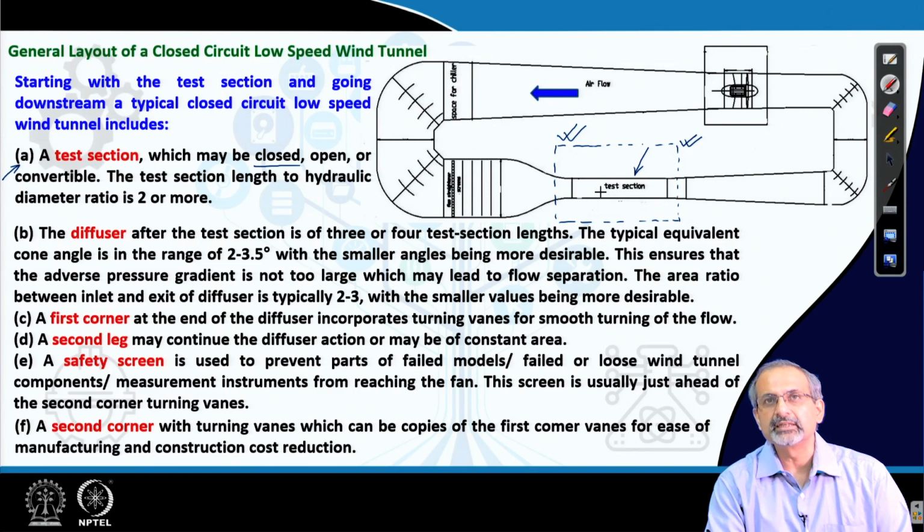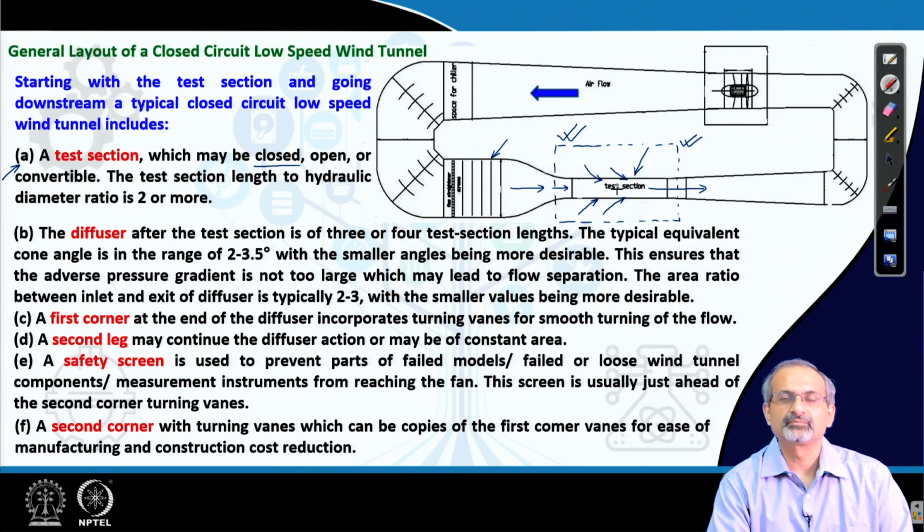Additionally, in open jet facilities, if you do not have an enclosure around the test section, there is often a problem that instead of the air coming in from the settling chamber and the contraction section, a large part of the air gets dragged from the ambient into the jet and then continues into the diffuser. Therefore, the jet gets extremely disturbed. Therefore, having an enclosure, an airtight room, is always a better idea in that case too.